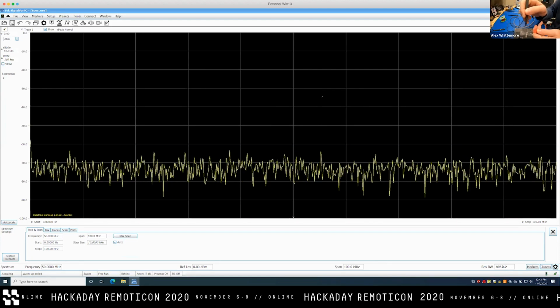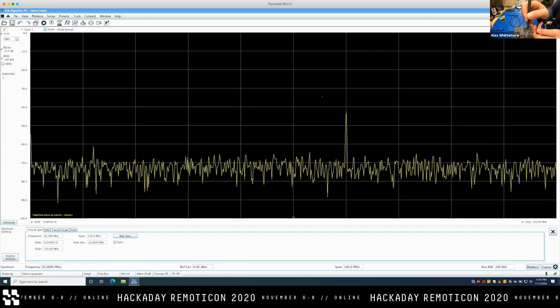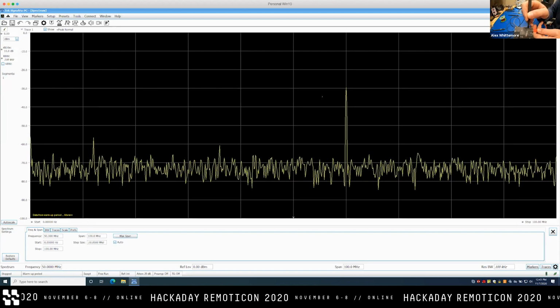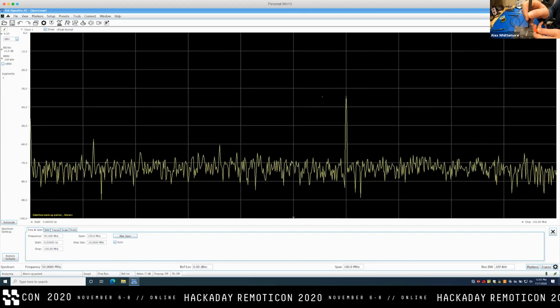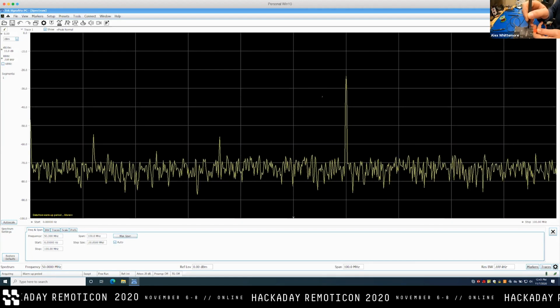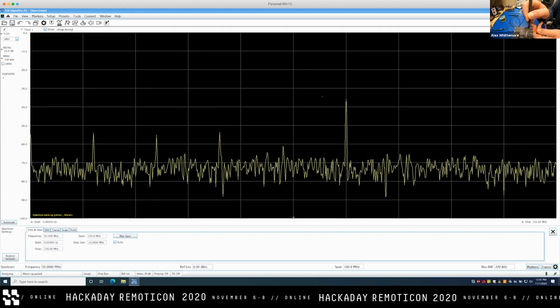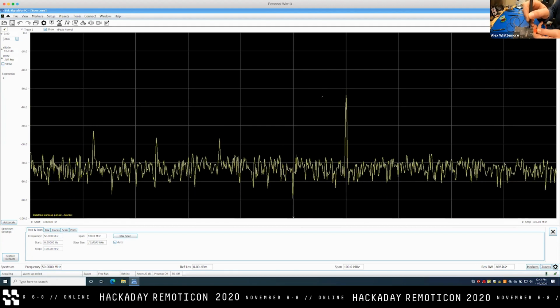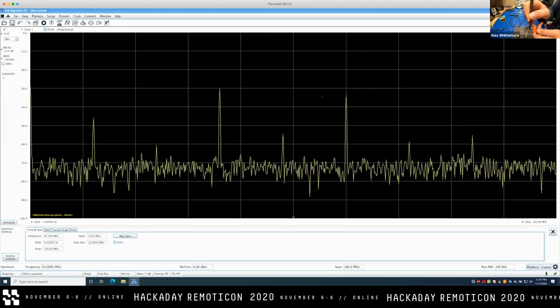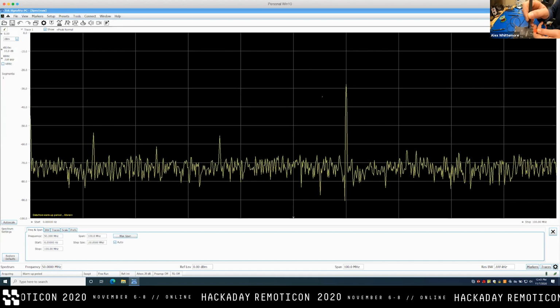If we move the probe orthogonal to the trace, so we're basically putting half of the current transformer next to the individual trace we're trying to measure, we can basically, with this probe, pick out nearly which pin specifically is actually emitting all this noise. And interestingly, we can see some new and interesting noise on other individual pins. But that's what's going on over here.